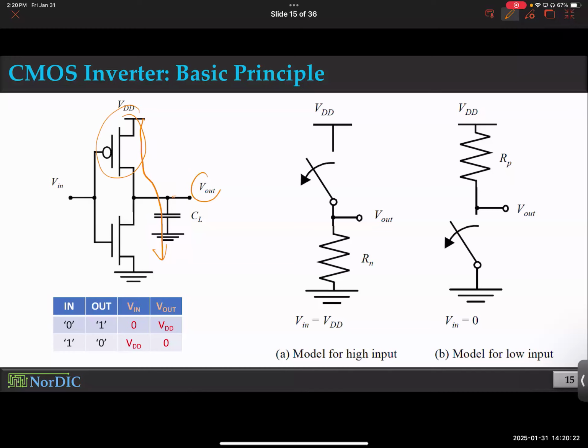So that means this becomes VDD when you charge it up. And VDD is represented as logic 1. Even if your VDD is 0.5 volt, we represent that to be logic 1. Similarly, when you discharge that capacitor down to ground, you get 0 volt almost. And that 0 volt is typically representative of Boolean logic 0. Does it make sense? So essentially 1 and 0 represent whether the capacitor is charged or discharged.